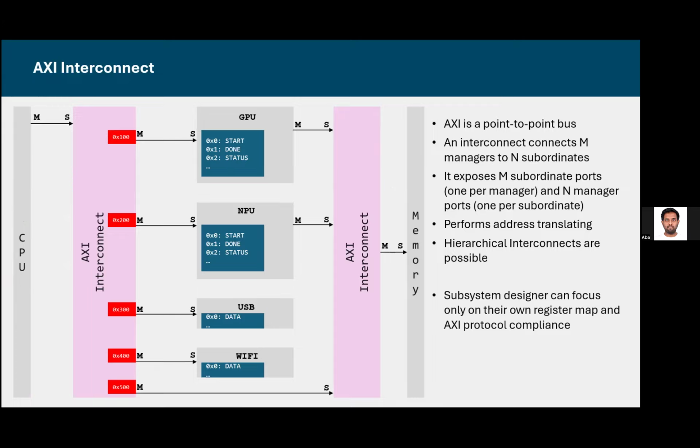So if you are writing an NPU, then you will be writing only your own configuration registers. The start, done, status, you will only do those things. You don't have to write anything else, and you don't have to worry about what your address is going to be and all of that. In general, that will be done by the integration people, who map these addresses and do the rest. The integration team will put everything together.